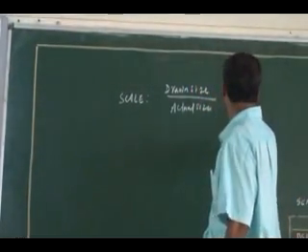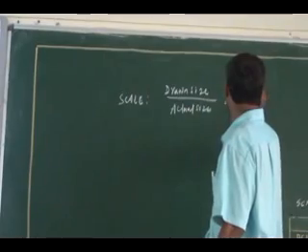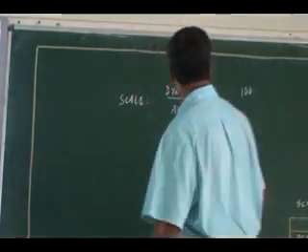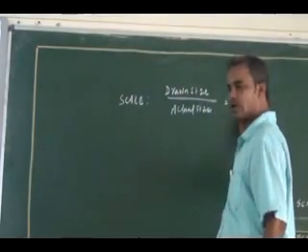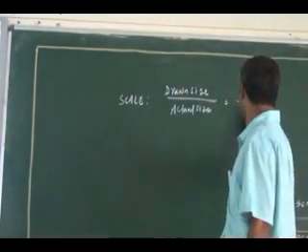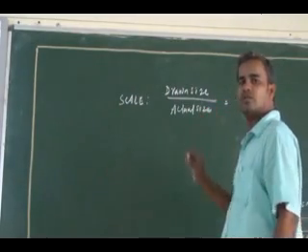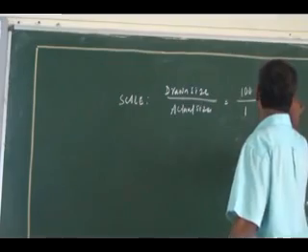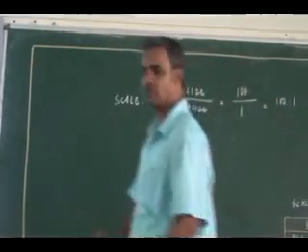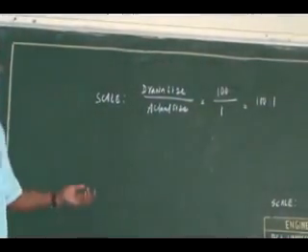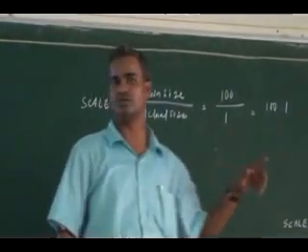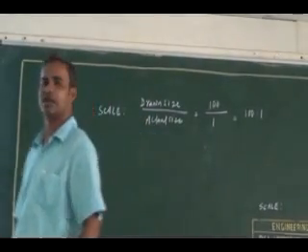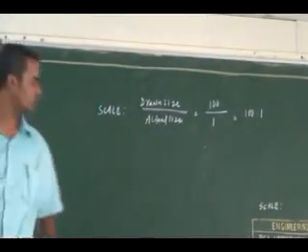If I am going to enlarge it, I will draw that 1 mm as 100 mm on my drawing sheet. The actual size of the gear's outer diameter is 1 mm, so the ratio will be 100:1. Any scale written as 2:1, 5:1, 10:1 or 100:1 is an enlargement scale.